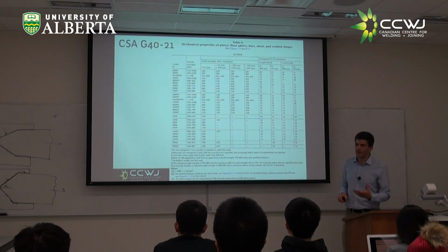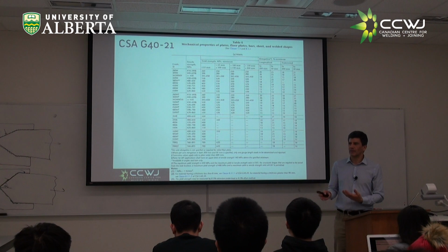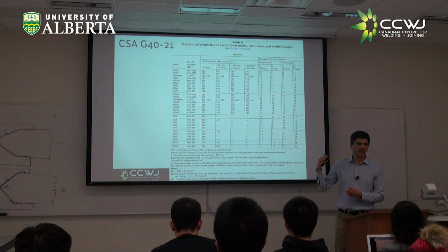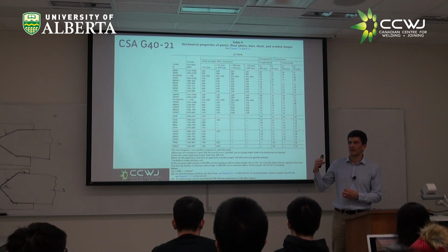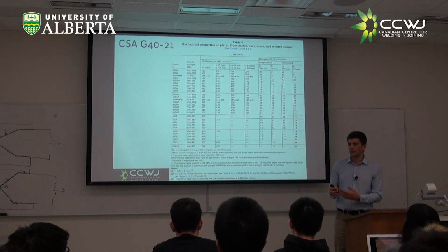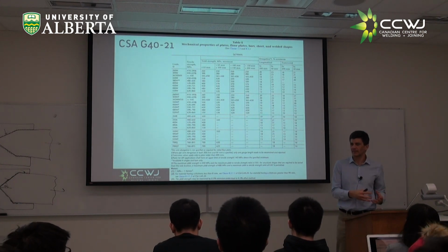Remember that this thing of matching is not an exact science because it's all based on standards. But when you do a procedure, you can have higher or lower heat input. If you have two heat inputs and one is higher than the other, what do you think the effect on strength is going to be of a high heat input? Lower, right? Because high heat input means lower cooling, which means fewer of the hard phases and more of the soft phases.